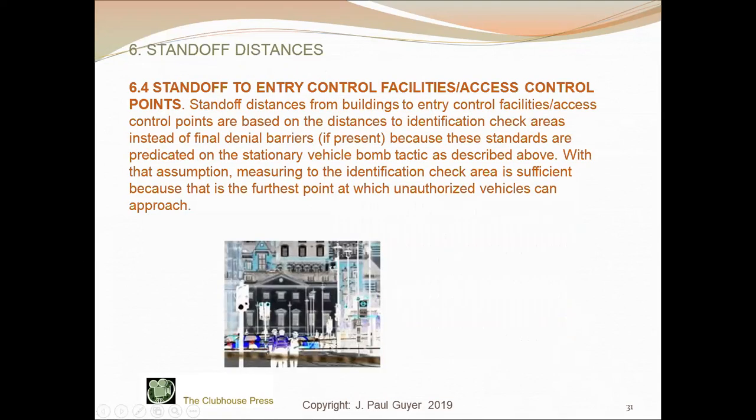Now, the standoff distance to the entry control or access control points. Standoff distances from buildings to the entry control or access control point are based on the distances to identification check areas instead of final denial barriers if present, because these standards are predicated on the stationary vehicle bomb tactic as described.